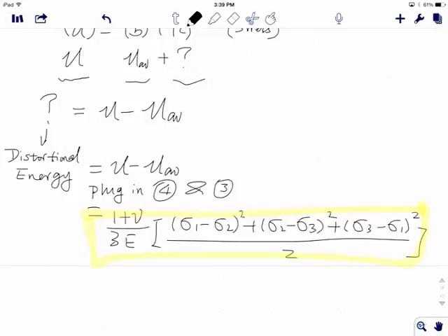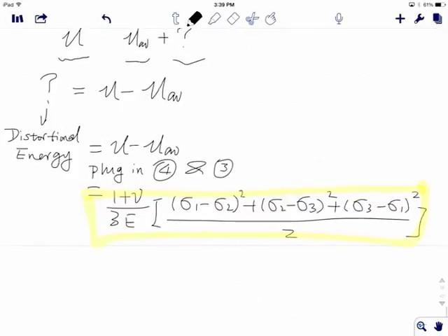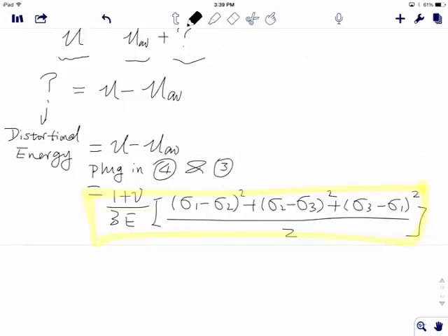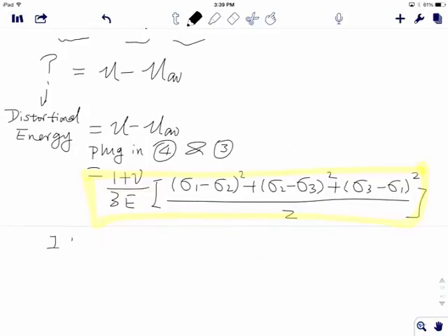what is the distortion energy caused by arbitrary loading in a unit cell, right? One thing we can check is, what if you have average loading? Your three-dimensional loadings are the same, right? You have 10 megapascal on the one axis, 10 megapascal on the two axis, and 10 megapascal on the three axis. Then let's see what the distortion energy is.